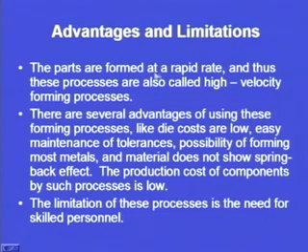The parts are formed at a rapid pace. So the production rate or production volume in high energy rate forming processes is higher as compared to the normal processes. The parts are formed at a rapid rate, and thus these processes are also called high velocity forming processes. The process is not slow, it is a very fast process, so the production rate is very high. There are several advantages of using these forming processes. The first one is that the production rate is high, because these are high velocity forming processes.